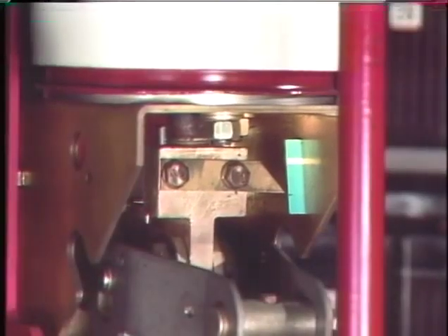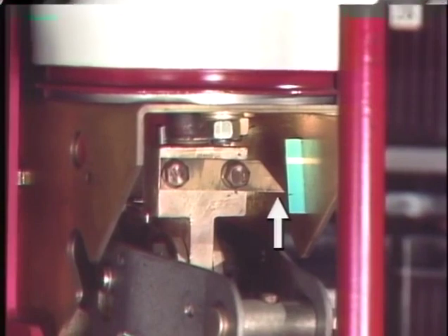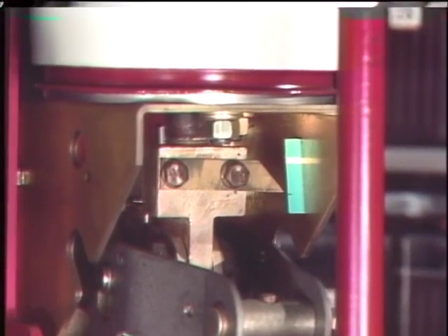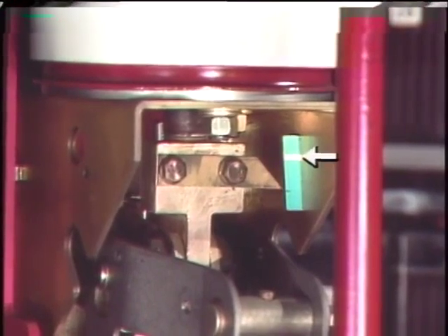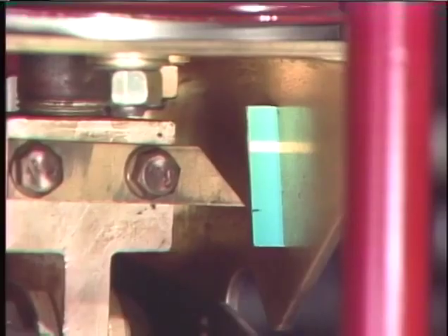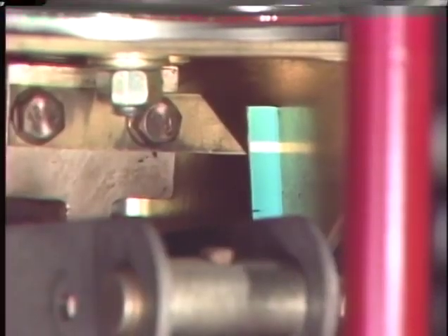An erosion indicator includes a pointer, which is mounted on the stem of the moving contact, a fixed target on the interrupter support frame, and a narrow band on the target. To check contact erosion, the breaker is closed. For a new vacuum bottle with the breaker contacts closed, the pointer should come up to the bottom of the band on the target. As the contacts erode with numerous breaker operations, the pointer moves up into the band, indicating how much contact surface has eroded.